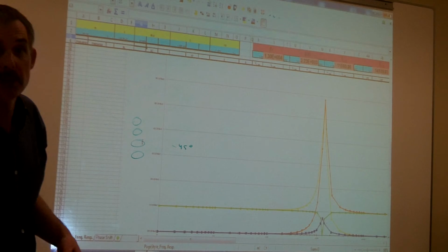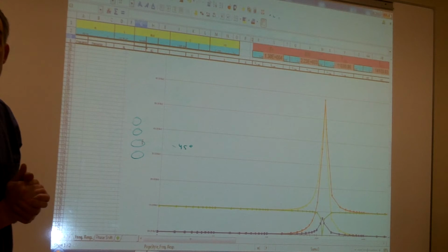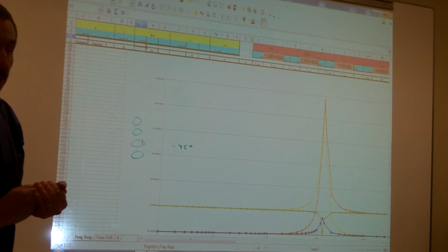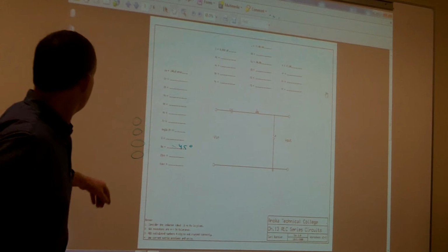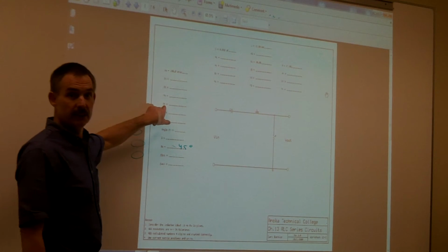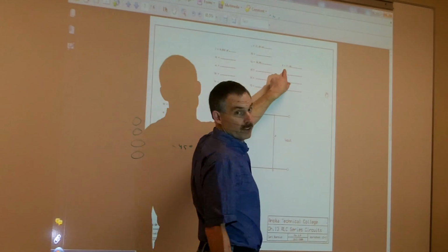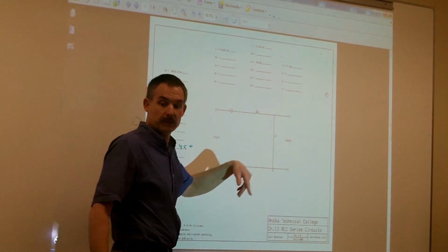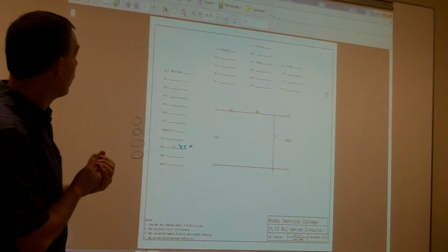I don't see how the resistance of the windings would affect the bandwidth. Isn't that the resistor value? Nope. We kind of ignored the resistance of the windings. No, we didn't. Because remember, we calculated out RT. Yeah, right, okay. And so we included the resistance of the winding and the resistance of those things. Since you take your outputs across the resistor, that resistance will be within the inductor.